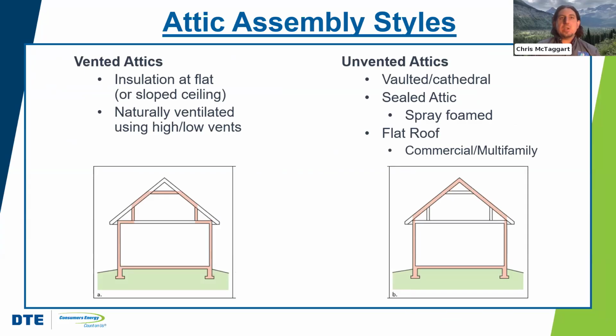We can do vented attics, which means that there is actually venting to the exterior, usually through a combination of eave vents as well as some amount of roof venting, and then unvented attics, which is exactly what it sounds like, basically where you don't have venting. Generally speaking, that's going to occur with a sealed attic, so generally spray foam, although you can use other insulation materials such as a netted and blown type of assembly, possibly.